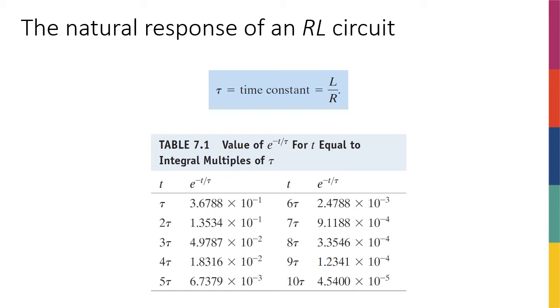So it depends on the size of my energy storing component, which is the battery or the capacitor or the inductor, and the rate that I'm burning energy, which is really the R, right? The higher the current, the more the R is burning energy, consuming energy, wasting energy, right? So the higher current it has, the faster it's going to burn the energy. So it has something to do with L and R for an RL circuit, and it has something to do with R and C for an RC circuit that we're going to talk about later, right?